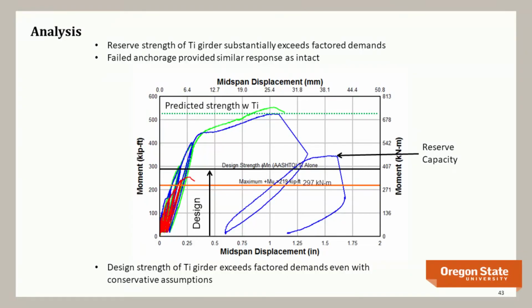If we test the girder by failing it first, I will actually get the green line. If I apply the titanium without testing it first, I get the blue line. The stronger beam is actually if I fail the girder first and then apply the titanium. And the reason it's better is you get the steel out of the way, right?